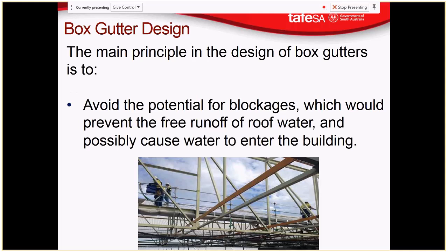This is not a very attractive way of building one, but we have our downpipe coming down here like this, but it doesn't go all the way, and instead we tee off, say there, for example, and then that goes down. You would do it flush with the wall. This is a very unattractive way to do it, but it shows diagrammatically what's happening. We have a screw cap on the end, just one of your UPVC screw caps that you use for an inspection point or anything like that.